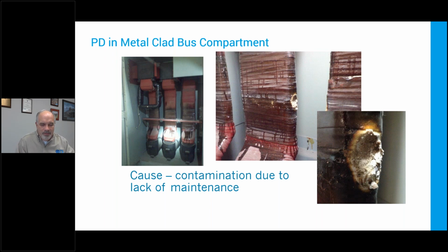Here's an example where a customer had some equipment out in the swamp and they never cleaned it. They had a horizontal brace, as you can see in the left picture, going across there, and all kinds of dust buildup. Now, dust isn't typically conductive, but it traps and holds moisture. Once it did that, the area between the bus bars had a different field strength distribution.